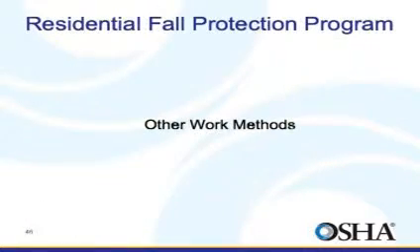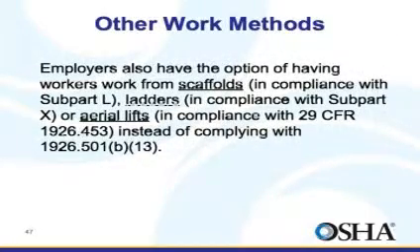Now we'll take a look at some of the other systems and processes that some contractors are using throughout the country to meet the fall protection challenges in residential construction. Now, we all know that the first principle of mishap prevention is to eliminate the hazard whenever possible. If you cannot eliminate it, you have to minimize its effect. We cannot eliminate working at heights in construction, but using ladders, scaffolds, and aerial lifts can help employers eliminate some falls from 6 feet or higher.